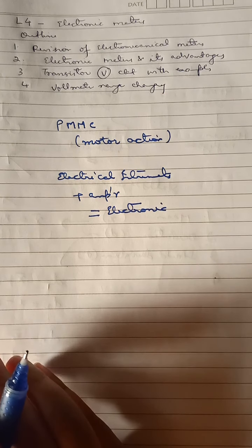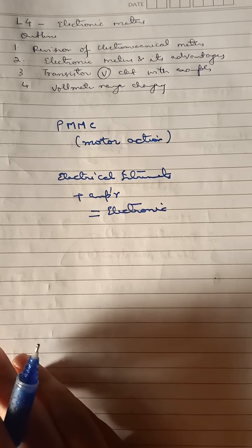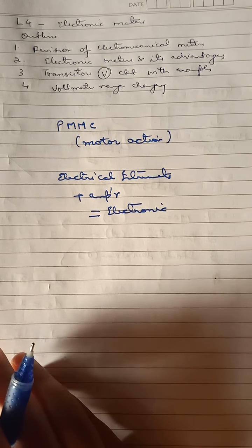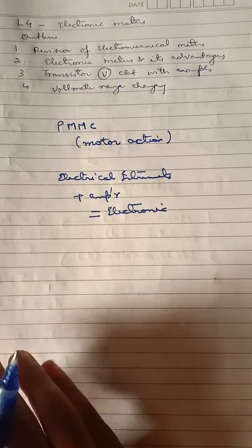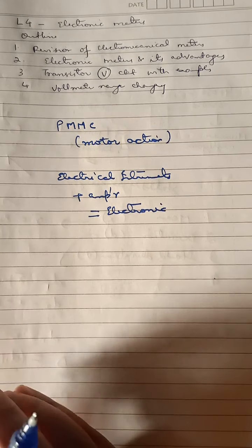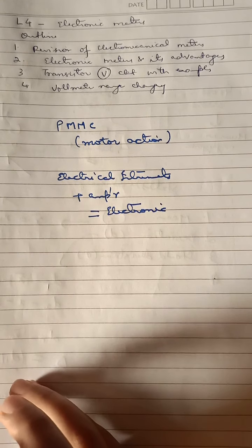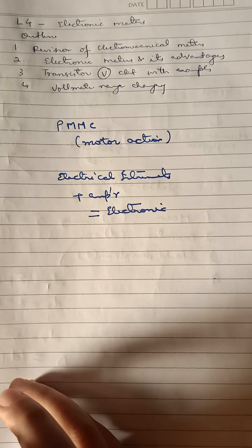Also, in a voltmeter the desirable condition is that it should have infinite resistance. Even if it is not infinite, practically it should be as high as possible. But with an electrical instrument, it has a certain amount of resistance, and it is not that high. If it is not that high, that means it can load your circuit.